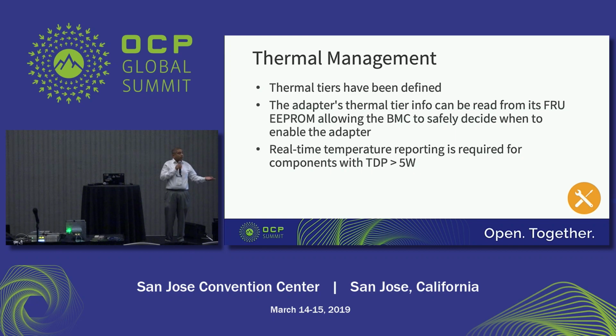You can allow it to be read from the BMC side, the live temperature. Also, NC-SI 1.2 is where we are going to have temperature reporting functionality added. So now you have standard interfaces, whether you come from RMII-based transport or MCTP, you're able to get this runtime temperature across the board, for the chip as well as the optic module.